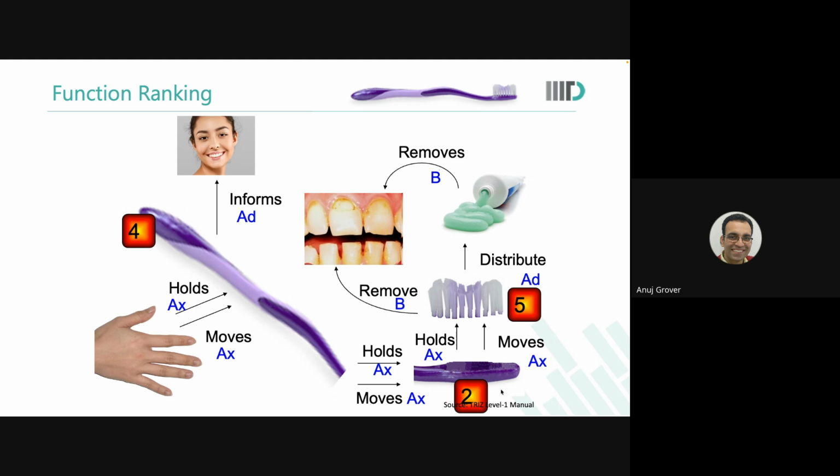So now, you see, every component I can give a score. Score of the bristles is 5. Why? Basic function plus additional function. Head only 2. Handle 4. Also it has an additional function there. Now, if I have to reduce the cost, I would want to reduce the head somehow.